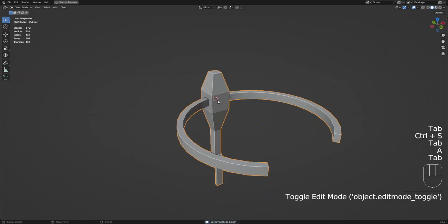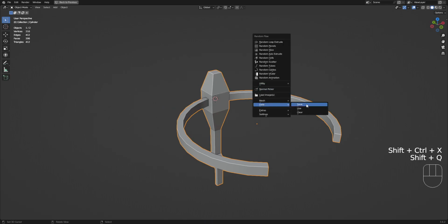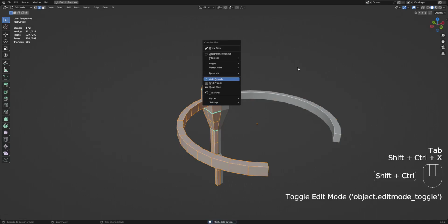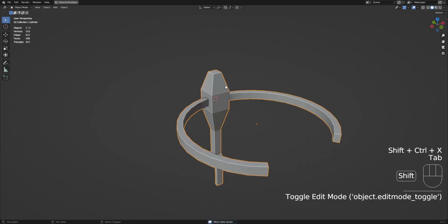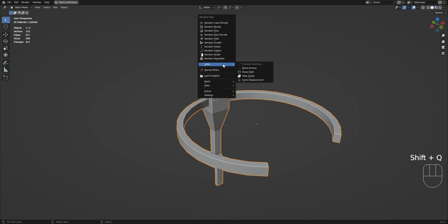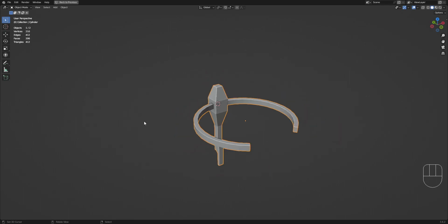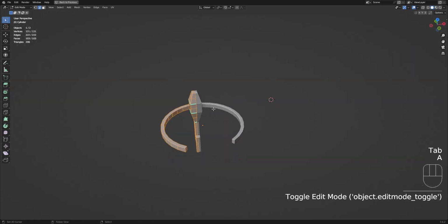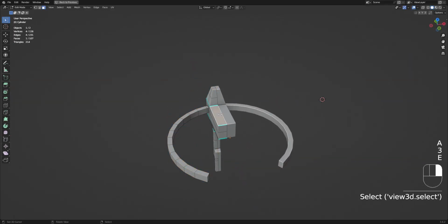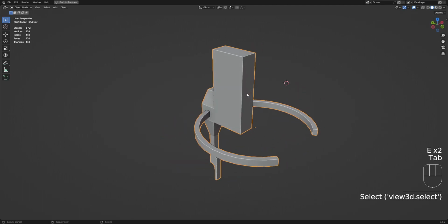Next up, I'm going to save this base mesh using data save in Random Flow, because I'm going to use a destructive operator for this, not a non-destructive Random Flow operator. I'm going to use Plates and Sets, which is a destructive method of detailing the object. So we save the data and we can reuse it again even if we mess up this mesh data here.